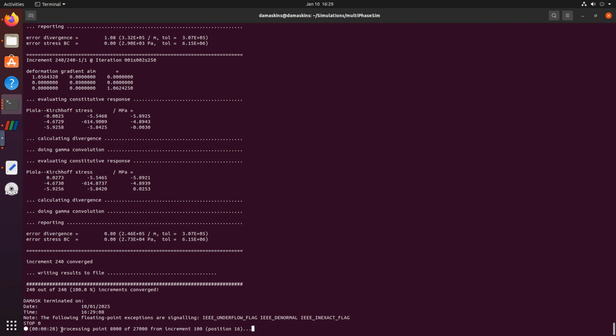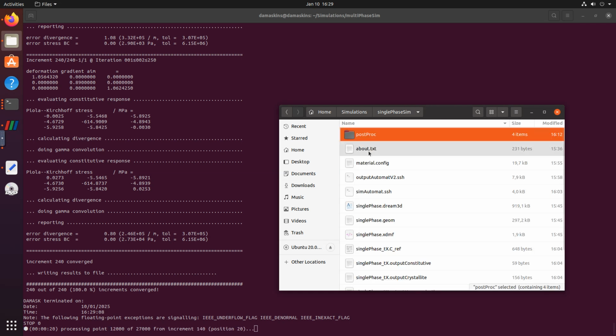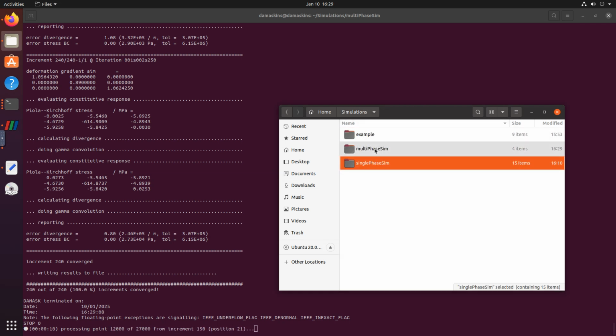And then, for example, you can also use these scripts in different configurations. Now, for example, if I have one folder in which I have 15 folders containing individual files that I need to run simulations on, I just need to run one script to say go into each folder, run a simulation, post-process the results, and then continue to do that until you've run simulations in all the folders, right?